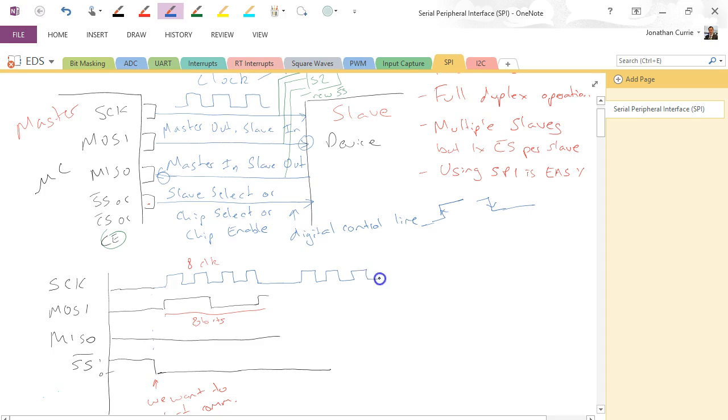But most importantly, what has to happen now is that even though I have sent effectively 0x00 here, now because the slave device has received an instruction here, so this is, let's say, an instruction or a command that we want it to perform, it now sends back some information. So this bit here is our received instruction. Once again, this whole bit is 8 bits.